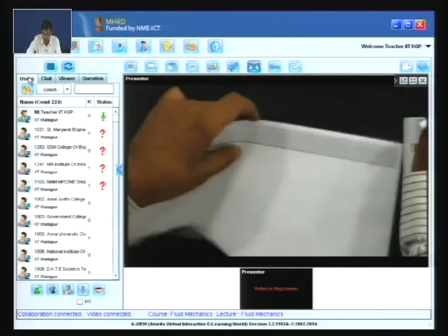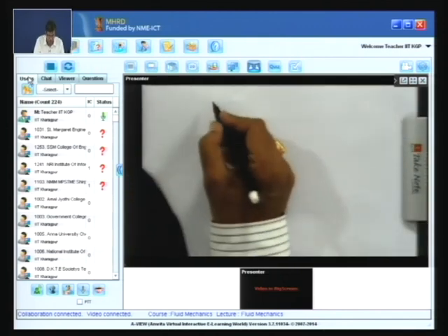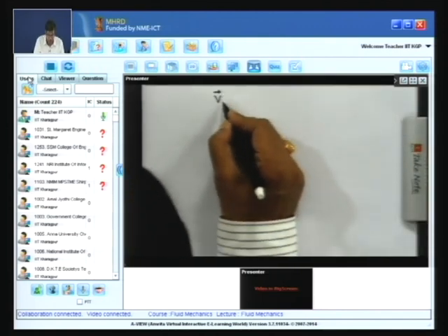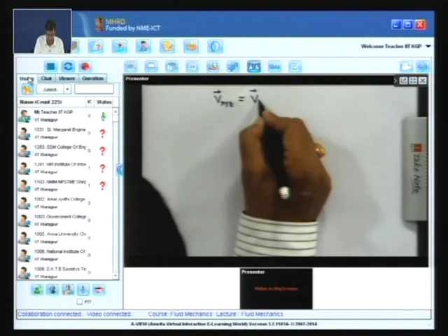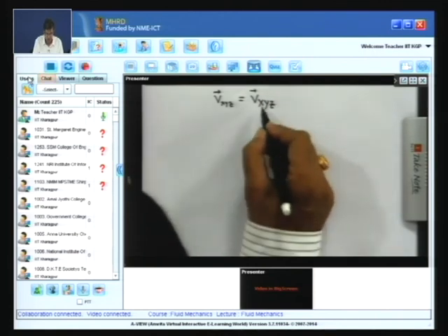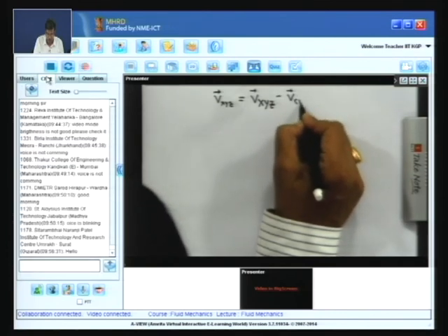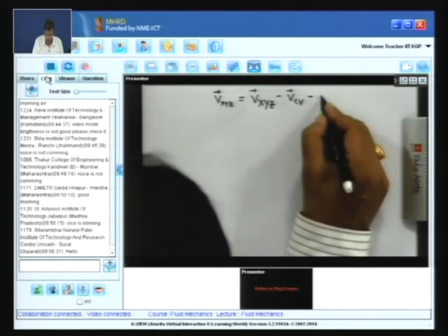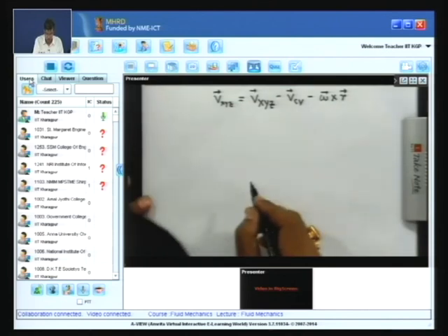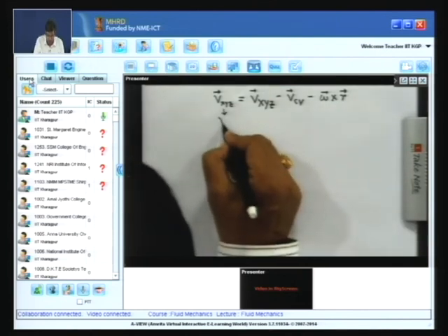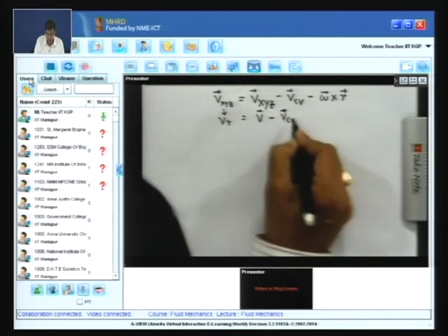So what do we get? For velocity we get that Vxyz, which is our relative velocity, is the capital XYZ velocity, meaning the absolute velocity with reference to the inertial frame of reference, minus the velocity of this CV, minus omega cross r. This Vxyz is our Vr and this is V. So we can write in our nomenclature, minus.